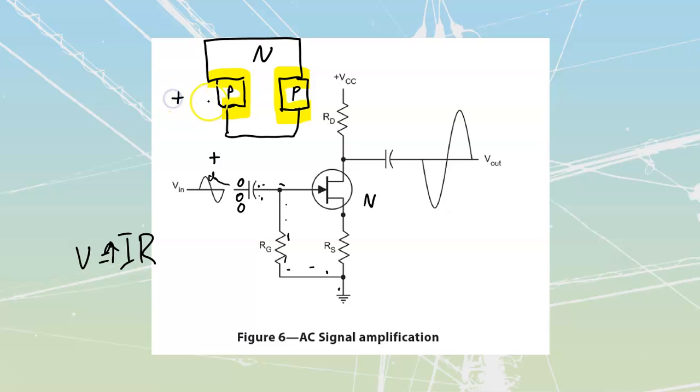As I increase my voltage applied to a P-type of material, I'm going to see my depletion region get smaller. So really, this depletion region is going to get smaller, which means that I'm going to open up this channel. Okay, so we've opened up the channel, which means my conductance has gone up, which means that my resistance for this has gone down.